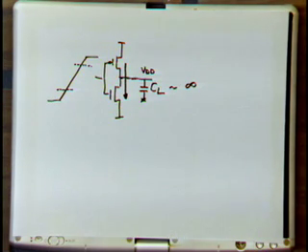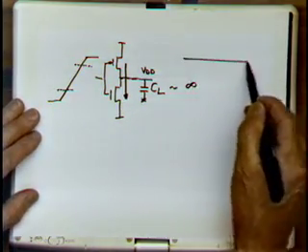What's happening when the capacitor is infinitely big? What's happening with the output? No. Definitely not floating. Oh, loading. It's loading. It's definitely loading. But what's going to happen with VDD? How fast will it move? It won't move at all. It's infinite capacitance. There's no way I can make it move. So this stays at VDD.